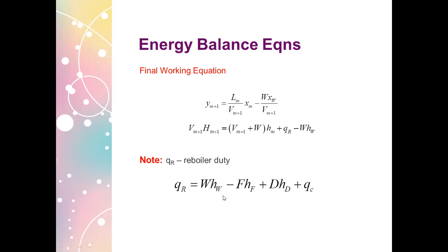That's what I mean. So you need an enthalpy diagram for this. In getting this, you need the mole fraction. So everything is just a substitution to this, as long as you know the mole fractions of these streams. And you know this by material balance.